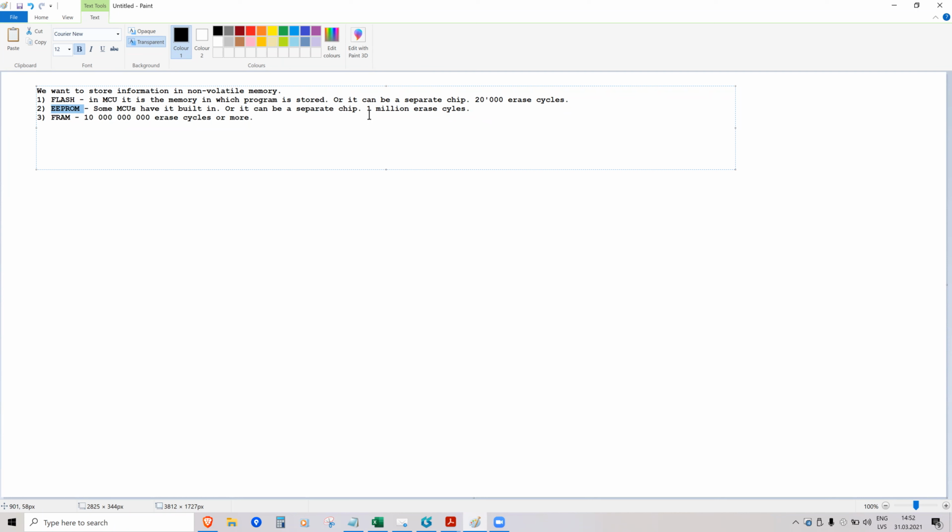And after some number of cycles, which is usually not really 1 million, usually it's maybe 10,000 or 100,000. But after some years, this dishwashing machine or something like that starts to forget the settings or doesn't work at all, because when it erases the chip, not all bits are erased, so wrong information is stored and some errors can show up.